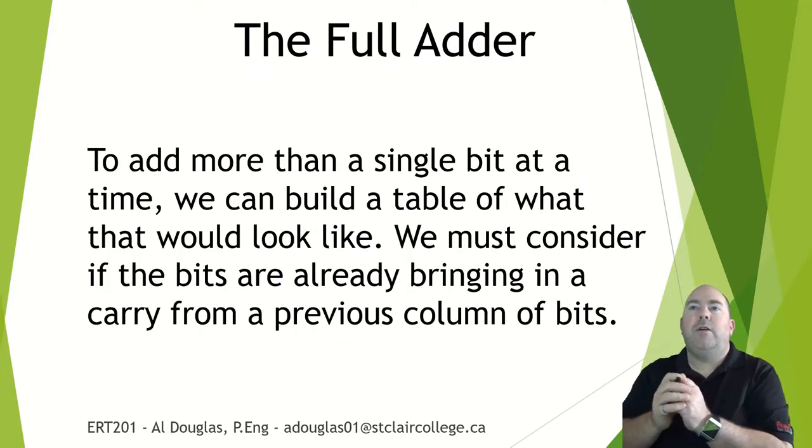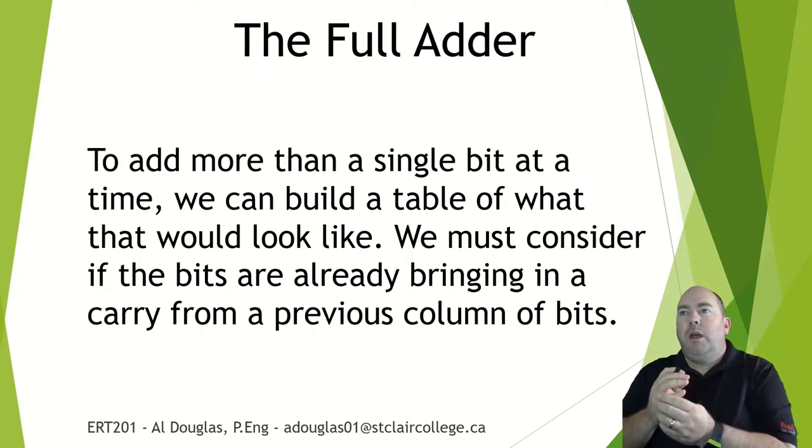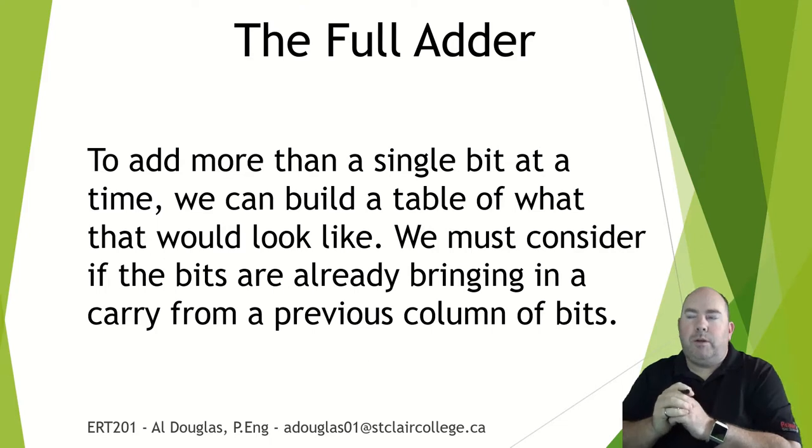The full adder. If you want to add more than a single bit together, you can build a table that will look like the one we're about to do here. So you have to consider if the bits are, basically which column are the bits in. Are they already bringing in a carry from the previous column?